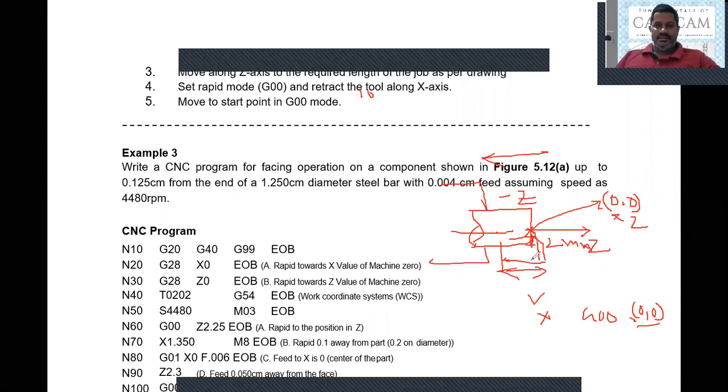This is the basic idea of how to write a turning program in CNC. This is what I followed in all the programs. In almost all the programs, I have given a 2 mm approach distance, and the depth of cut is not going to exceed 5 millimeters.